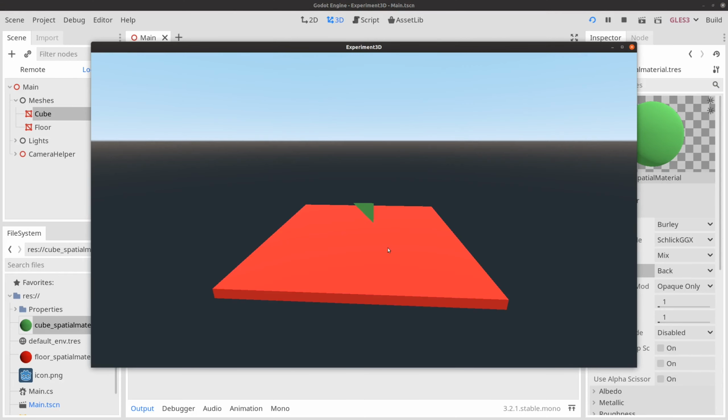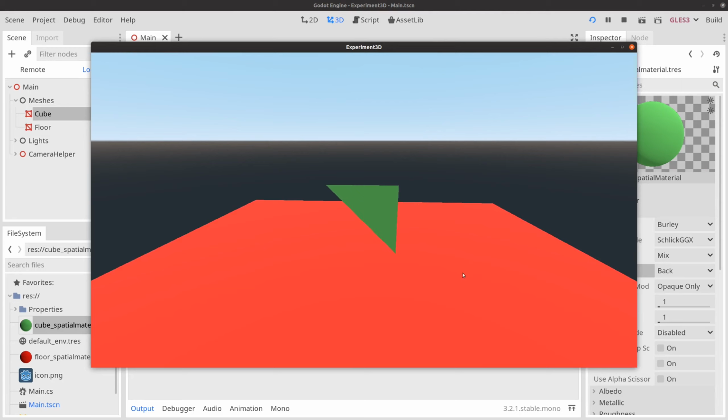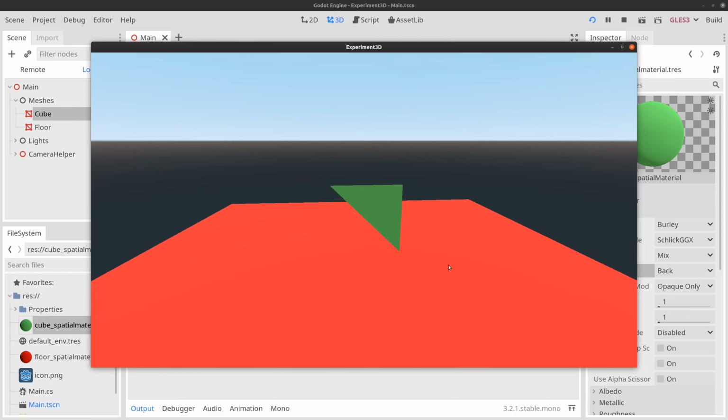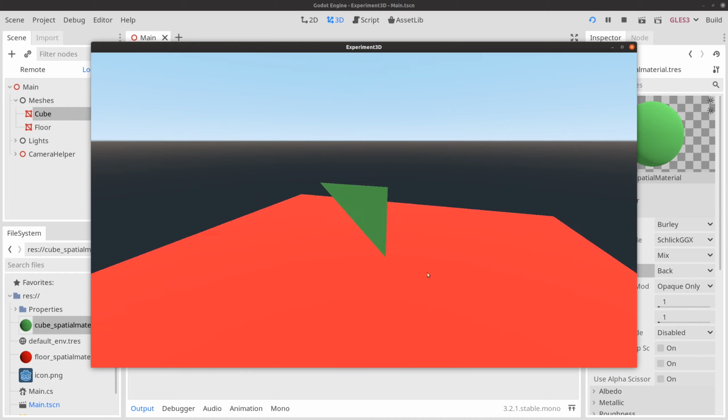And it's not. But if you rotate around, see, now because we listed it the other way, this is the front and the top triangle disappears. Hopefully you can see what's happening there. So that's why it's super important. If you're defining these yourself and you notice there are pieces missing, most likely you didn't wind the vertices in the correct order.